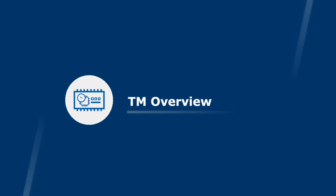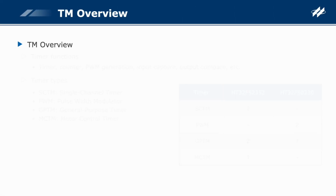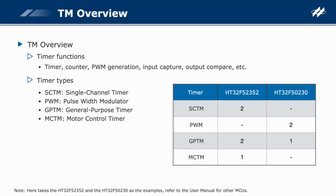TM overview. The TM, which stands for Timer Module, is an important peripheral in the HT32 MCU and appears in almost every application. From simple LED flashing control to complex motor speed regulation, timers provide an accurate time management mechanism, enabling users to implement various functions such as timer, counter, PWM generation, input capture and output compare.